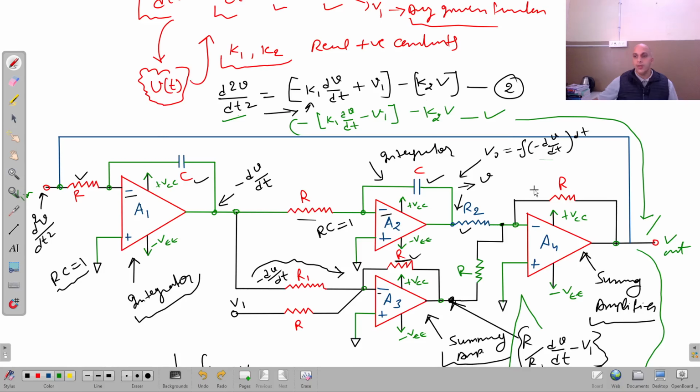So you can see here, if I connect this path to here, then the d square V upon dt square that I assumed in the beginning does not need to be applied separately. It will automatically come from here, and it will be supplied at this terminal, because you know very well that d square V upon dt square is equal to this function on this side. So this is appearing at this terminal and it is applied here. In this way, we will get the solution of this differential equation.